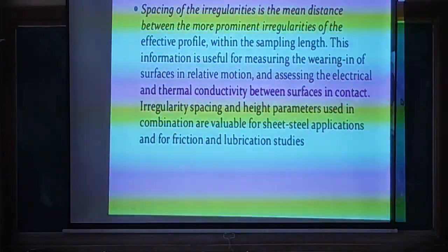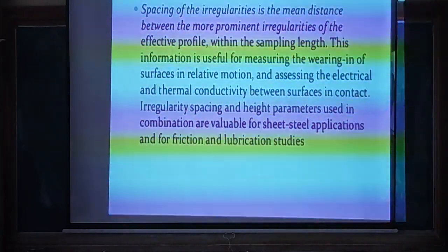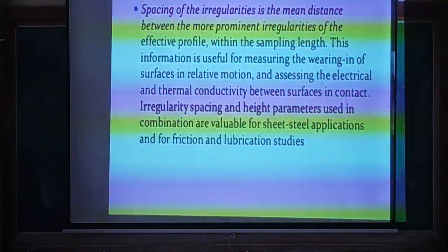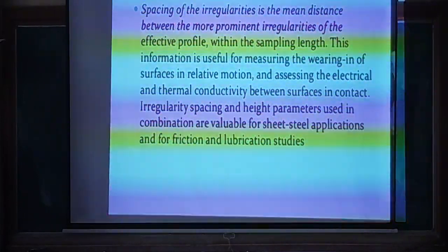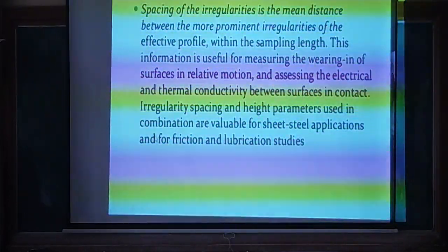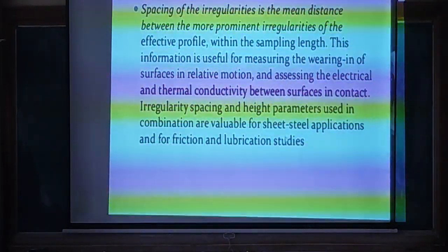Irregularity spacing and height parameter used in combination are valuable for sheet steel applications and for friction and lubrication studies.